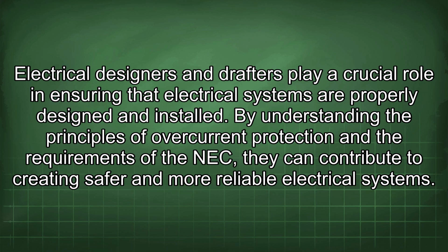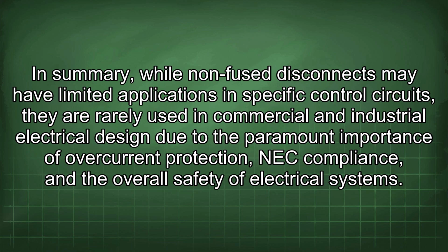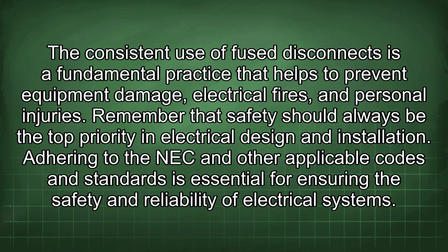In summary, while non-fused disconnects may have limited applications in specific control circuits, they are rarely used in commercial and industrial electrical design due to the paramount importance of overcurrent protection, NEC compliance, and the overall safety of electrical systems. The consistent use of fused disconnects is a fundamental practice that helps to prevent equipment damage, electrical fires, and personal injuries. Remember that safety should always be the top priority in electrical design and installation.